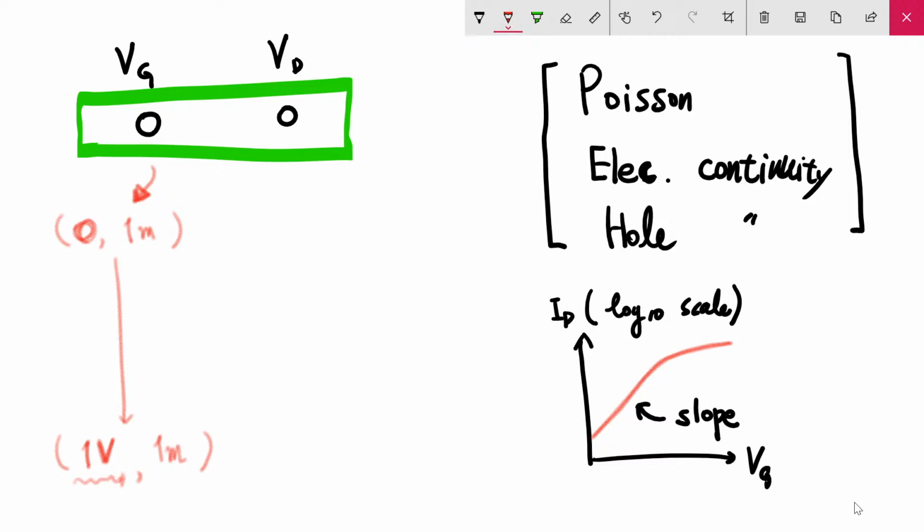Instead of stopping at 1 millivolt, first take the drain sweep. Increase your drain bias up to, for example, 1 volt. Even in this case, you will have a really negligible current because the transistor itself is completely turned off by this zero gate bias.